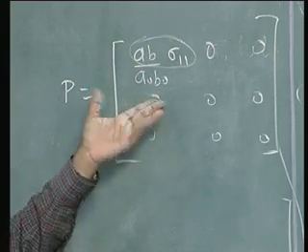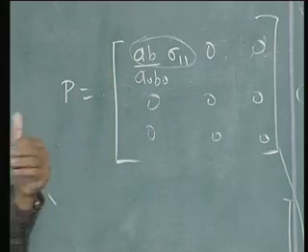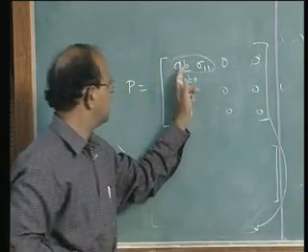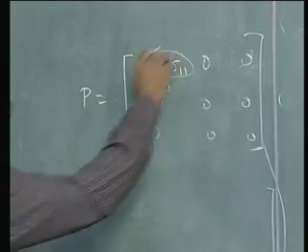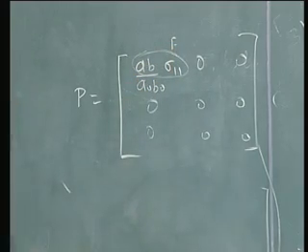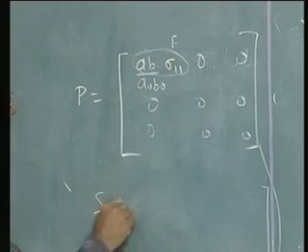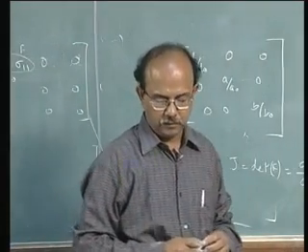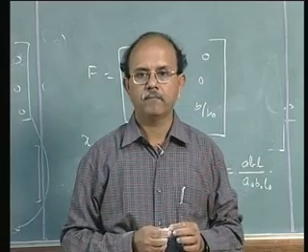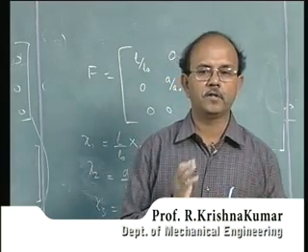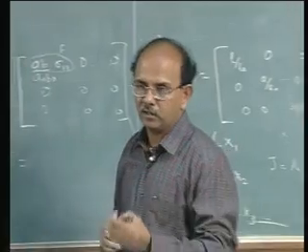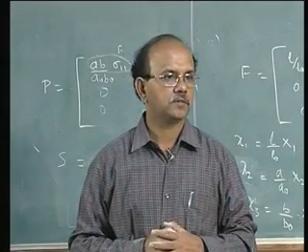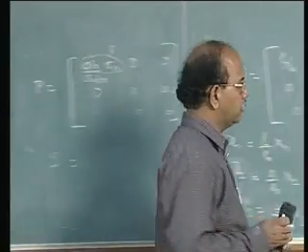So, obviously, I mean you could have guessed it, but nevertheless it is very important that you go through the whole steps, because that will give you the whole thing. So, this is the force divided by the original area would give you P. Now, calculate the second Piola-Kirchhoff stress. We already saw that it is the pullback that we have to apply on the Cauchy stress. So, rework that here.